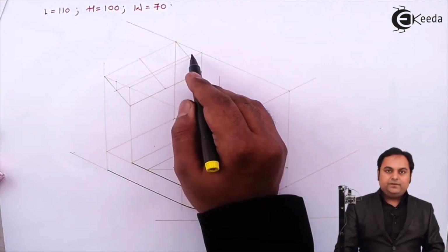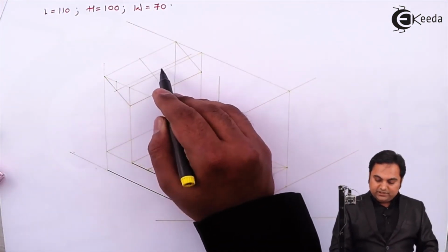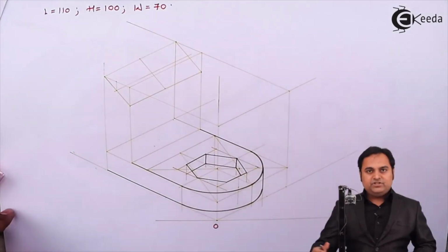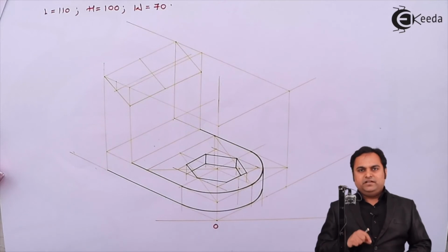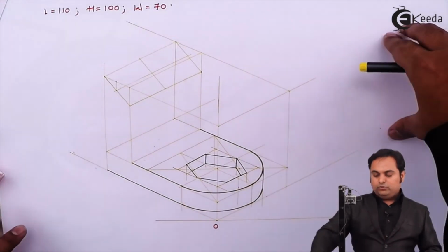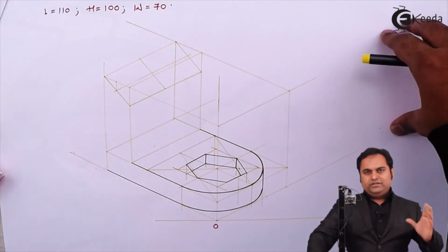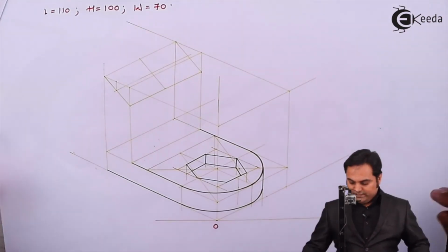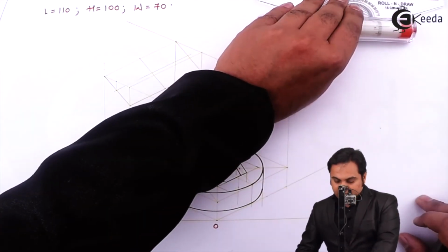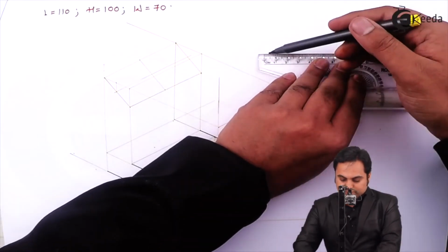So getting this line, now over this line the cut will be there, and as I have mentioned time and again that if the angles are given in isometric drawing, it is better to draw them, or draw it compulsorily, in a separate diagram and then project it back. So for that I'm drawing that surface on a separate view here.